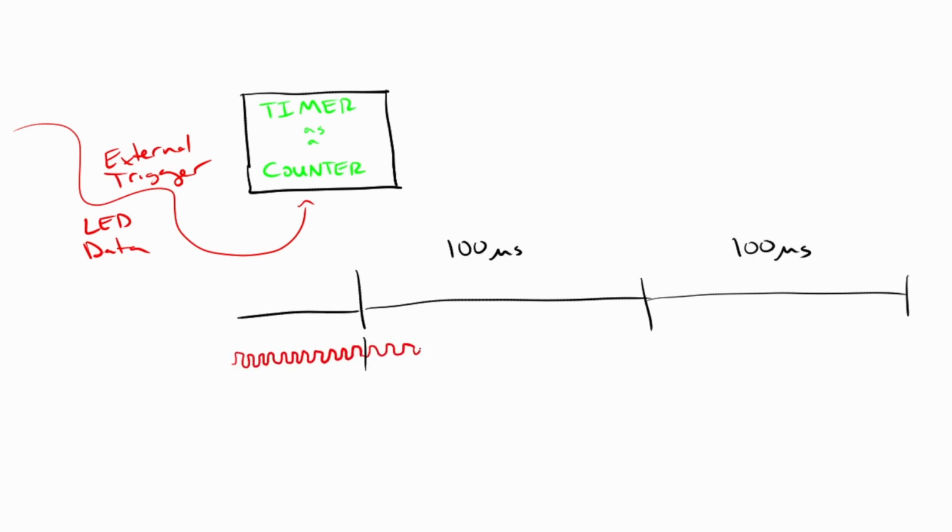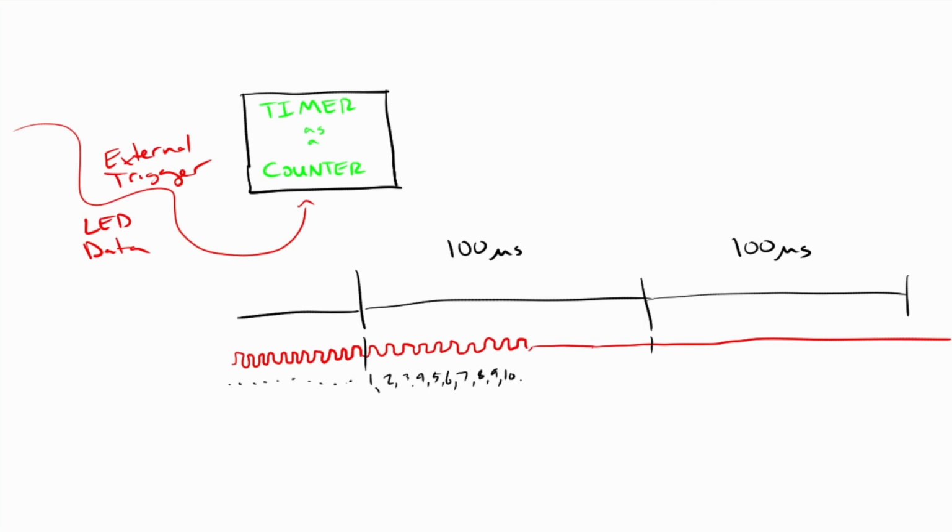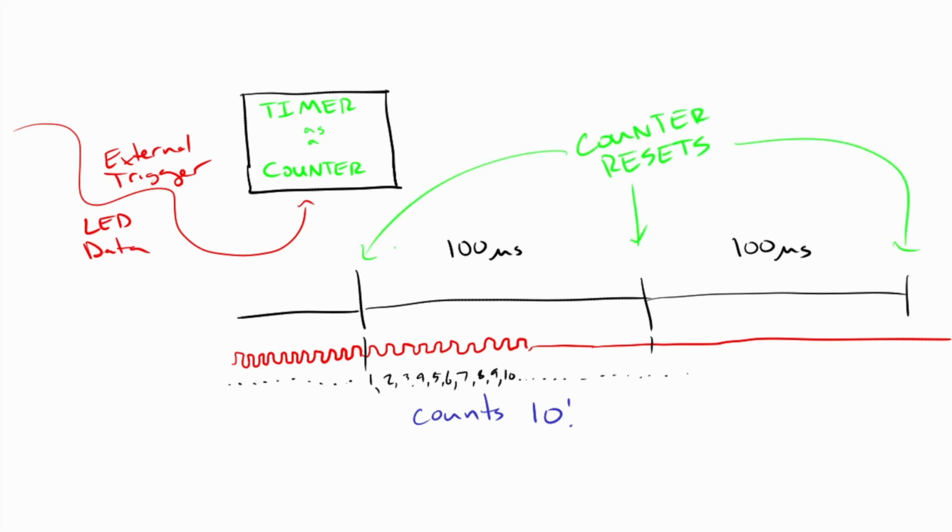So I just use this mode to count each edge in the 100 microsecond window, as defined by the low power timer. When the low power timer triggers, that is, it reaches the end of its window, I reset this counter. If this counter counts 0, reset the flags.